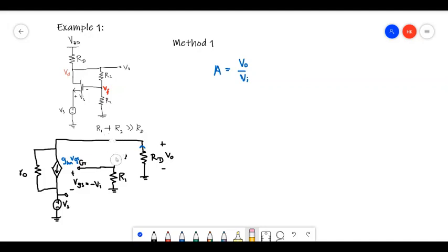So I'm going to remove these two resistors, and also I need to make the feedback voltage Vf 0, so I'm going to ground this. Now let's see how we can do this. I can also neglect this resistance, because it is a very large resistor and the current going through it is very small. So it is a very simple network now.